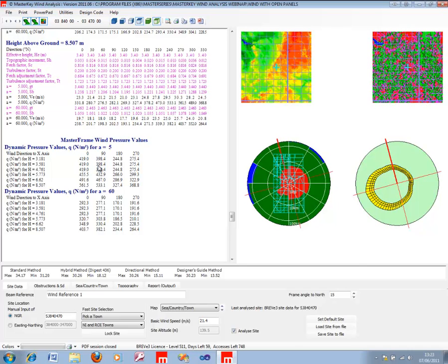We adhere to all those rules. We look at the crosswind breadth with regard to the height of the structure, and more than likely for a structure like this, which isn't very tall, I would imagine we'll be using the Q value from the top of the structure for the entire structure through the height of it, so we'll probably not notice any variation in Q through the height of the structure in this instance, but that is being considered for you.